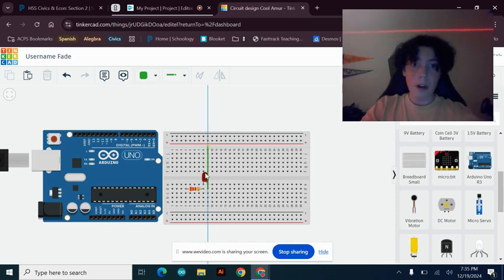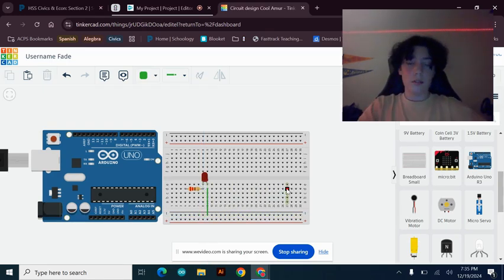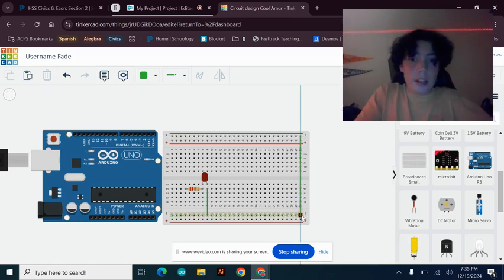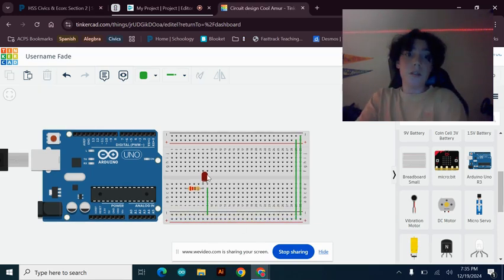So now you have a wire, and you're going to drag it down into the negative here. This is negative, so drag it down to the 9th column into the negative so that you can connect it. Now, it should look like this. Then take the negative here and connect it to this negative down here, so there's both the top and the bottom. Do the same thing with the positive, but take it from the row lower and add it to the row lower here. So it should look like this.